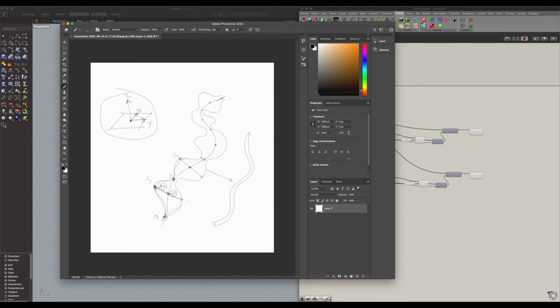And the way to do it is to create a section, for example, a circle is one of the simplest ways, and have those circles again perpendicular and parallel, so that I can run the command loft and make a pipe out of all these circle sections. And then later I can change the radius of these circles and adjust and control the thickness of this pipe.